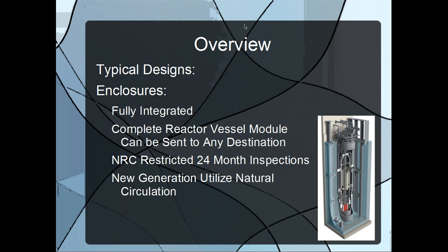Establishing reactor coolant flow through these vessels depends on a heat differential, and therefore a density differential, and gravity to produce natural circulation flow. As control rods are withdrawn, the nuclear fuel fission process is accelerated, causing a large amount of heat. The heated reactor coolant near the fuel then moves up through and over a tube called the riser section, which has steam generator tubing surrounding it. The steam generator water removes heat from the primary coolant, which then becomes more dense. This denser liquid is forced back to the bottom by gravity, and the fluid head developed by the rising heated primary coolant. The cooler liquid is then reheated by the fission process, and the flow continues.